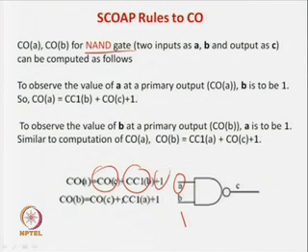So, this is there, and 1 for the level shift. Similarly, for B, A has to be made 1. So, combinational controllability of A to 1 plus you have to observe B via C. So, this is the case and 1 is added for the level shift. So, these are your rules for observing A and B for an AND gate.